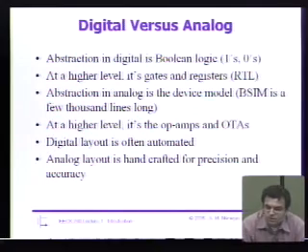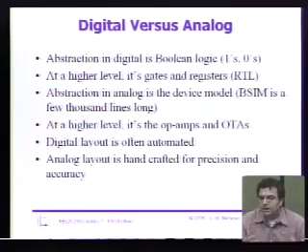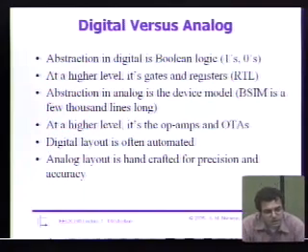Your transistors are your building blocks, and the way you understand your transistors is that these transistors are described by some model. Now, in your first circuits course, probably the model you used was something like a square law model for a transistor. We're actually going to use that model partially in this class as well. It gives us a lot of insight. It's very simple. But if you're going to do any kind of serious design, you have to use something more sophisticated. Today, that's some kind of transistor model. Often it's a BSIM model.